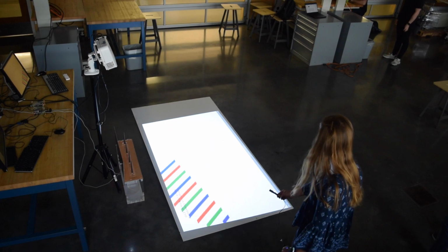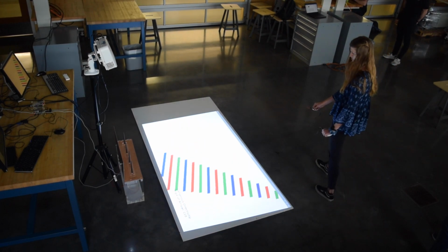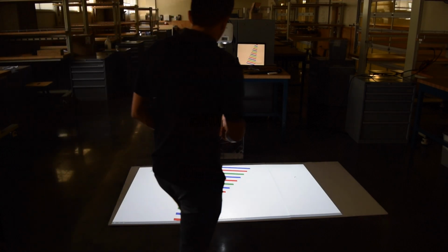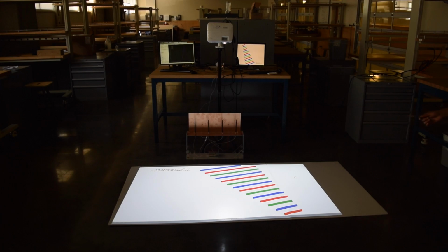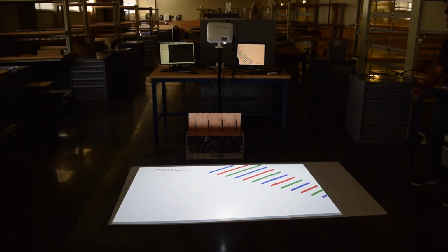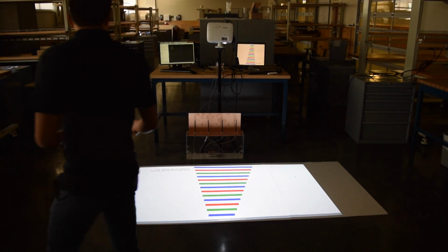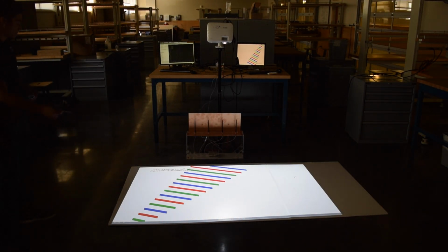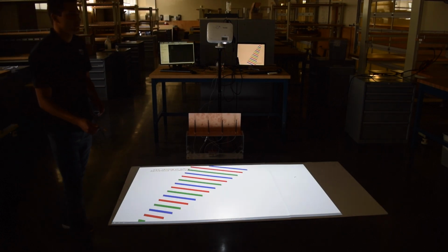As can be seen in our real-time example displayed before you, our simple 4-element antenna array is capable of steadily measuring from about 35 degrees to 145 degrees, a total range of just under 120 degrees on either side of the array. The antennas readily discern the incoming signal from several meters away. The code is capable of averaging the angles and outputting the angle to the user. We expect this application to aid classrooms of thousands of students and aspire at an earlier age to pursue STEM fields of study.